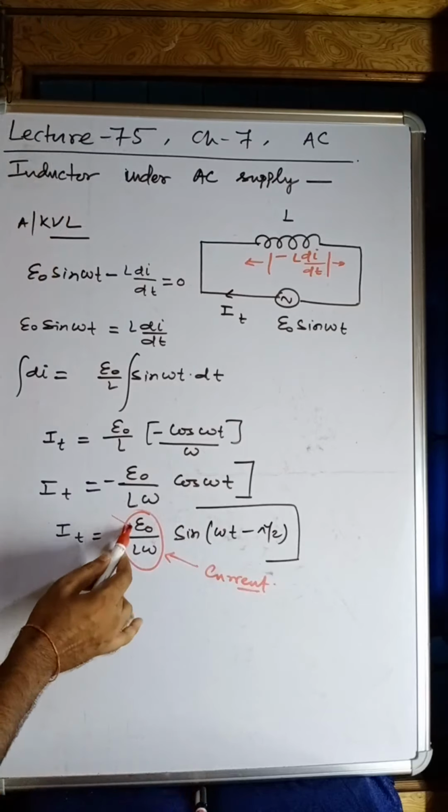Here, this inductive circuit, actually the inductor, blocks the AC. Inductor blocks the AC. Why? If this value is much higher, the current will be how much? Lower, almost 0. If this is very high, then this will be very small, approaching 0. It means what is this inductor doing? Inductor is blocking the AC current. Kindly note down in your notes, inductor blocks AC current. Okay, now let me discuss the DC current.